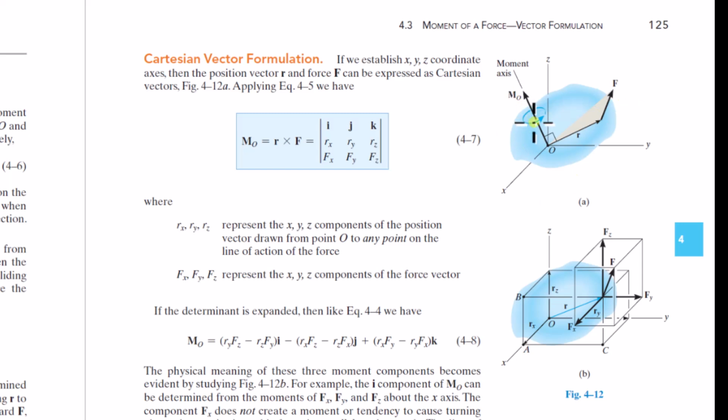If I change the position of this vector, then I'm changing the force. I have to change the position of this force relative to the point. I'm changing the loading on the body. I'm changing the problem, right? Because if I calculate the moment of this force about any of these points on the body, it's going to be a different moment every time. There might be a coincidence where some are the same, but in general, it's going to be different. So I can't just move the moment without changing the whole problem.